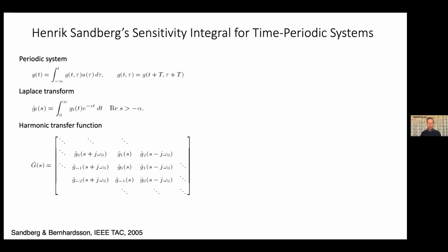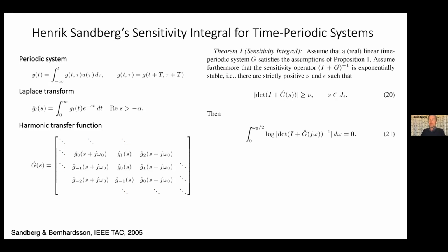So you see you have an infinite matrix basically expanding in all directions of this Laplace transform of the impulse response up there. So with this transfer function, we can compute the sensitivity function and then express the sensitivity integral in this form.